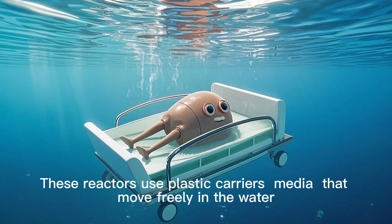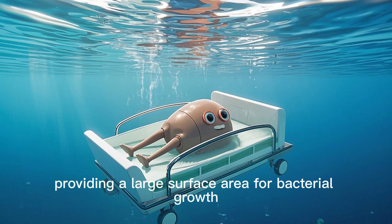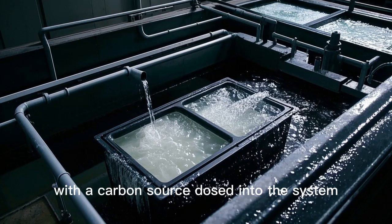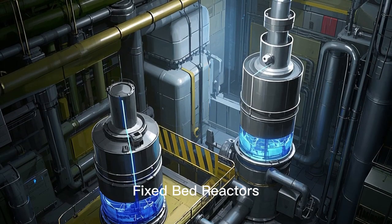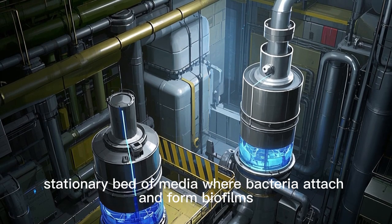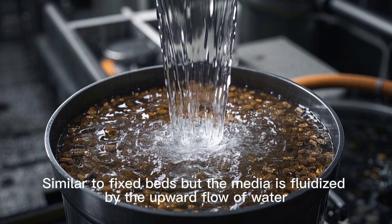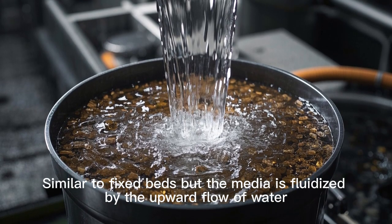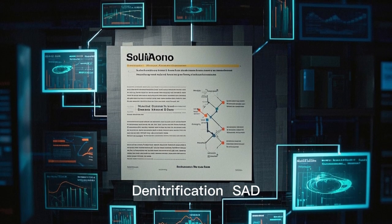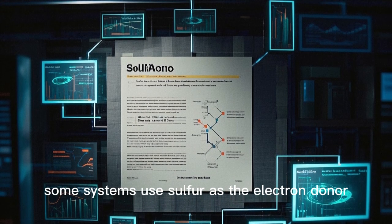These reactors use plastic carriers, or media, that move freely in the water, providing a large surface area for bacterial growth. Anoxic MBBRs are commonly used for denitrification, with a carbon source dosed into the system. Fixed bed reactors: water flows through a stationary bed of media where bacteria attach and form biofilms. These can be upflow or downflow. Fluidized bed reactors: similar to fixed beds, but the media is fluidized by the upward flow of water.